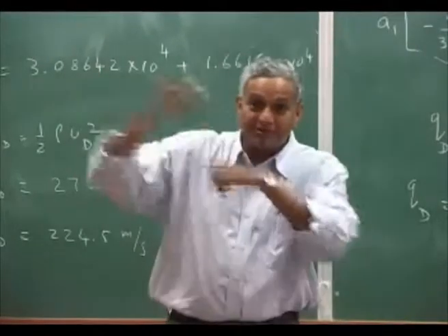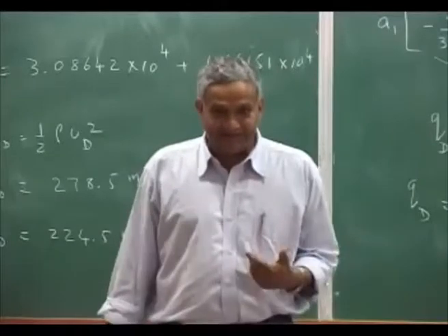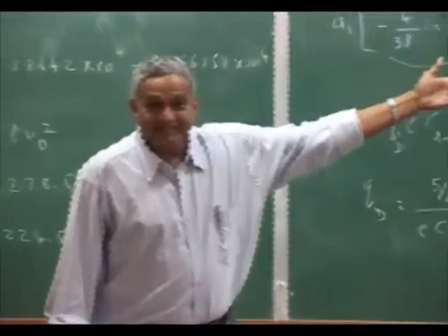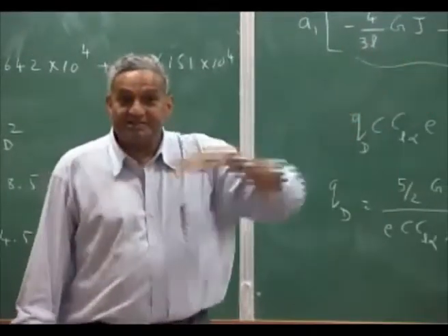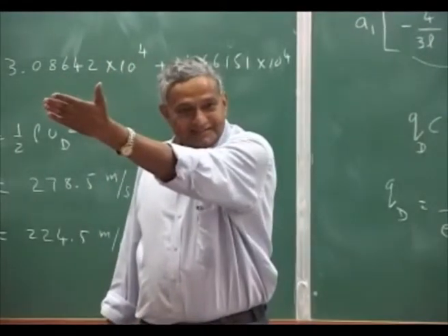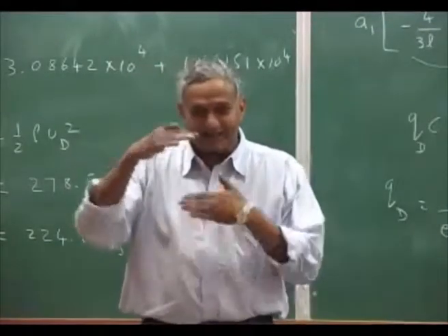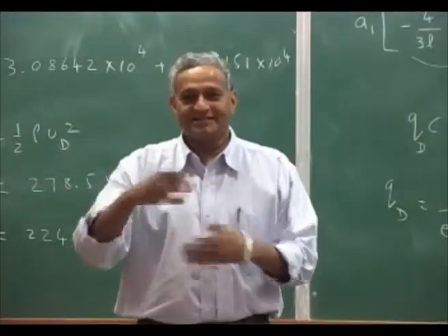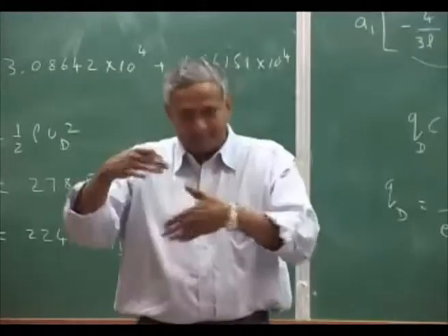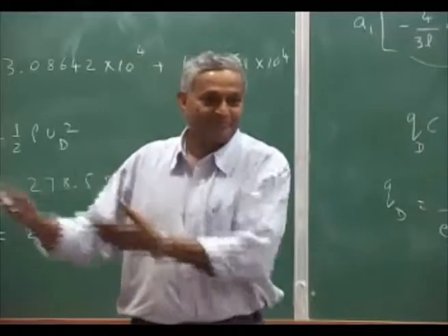But these two are coupled equations. You will find the bending deformation sitting in the torsional equation and the torsional deformation sitting in the bending equation. So they will be coupled equations, and you will have a 2 by 2 or whatever, depending on the number of terms which you assume, you will get that form.